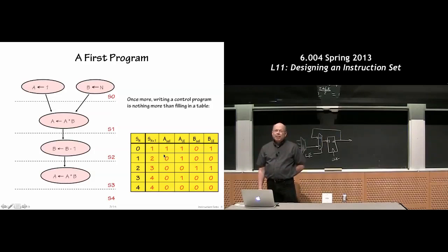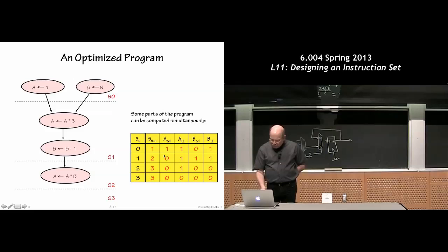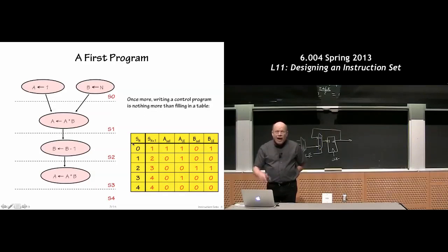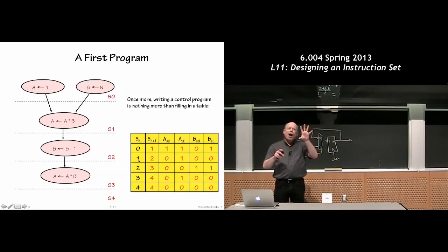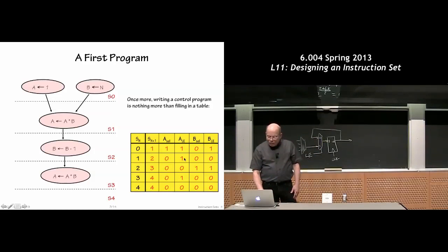It's a pretty simple recipe, pretty straightforward. Any questions about that? I mean, we're going to start complicating it here for a second. So think of this now as a system where we can basically embed this control table into one of our little FSM implementations, which consists of a ROM, which provides these output values, and a state register that provides the current state number, which is used as the address to look up what the value should be.